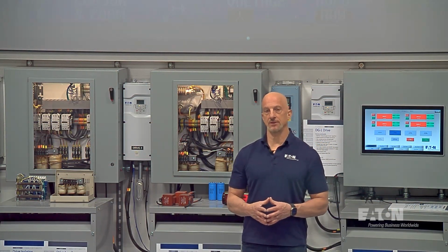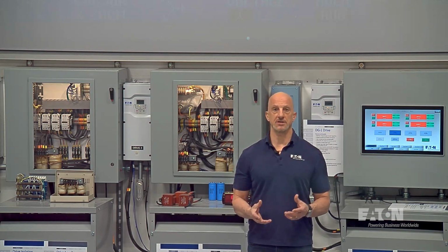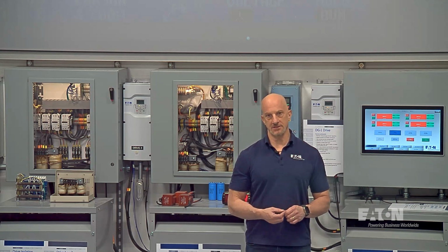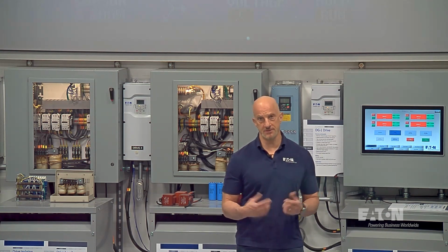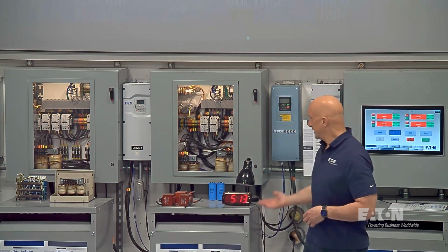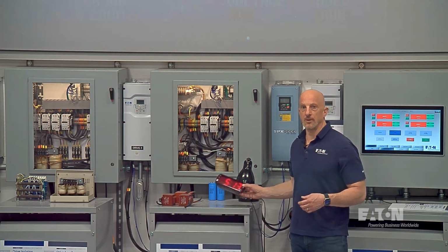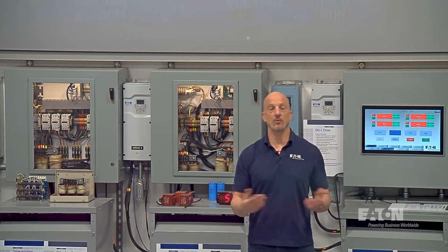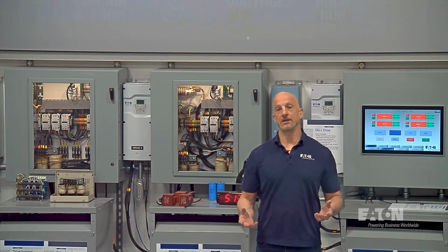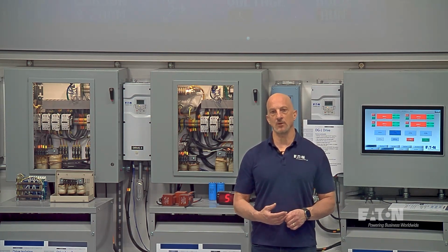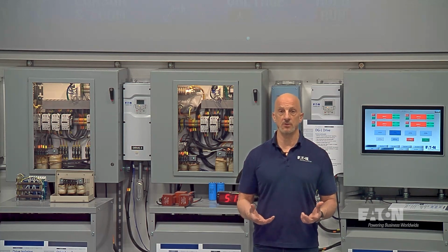So we've talked about multiple zero crossings with voltage distortion and talked about how that causes misoperation. The specific things that we like to talk about with multiple zero crossings are things like sine wave distortion causes things like digital clocks to misoperate. So we actually heard a story about digital clocks misoperating where the workers got to go home early. So I guess in some cases maybe it's not a bad thing. But in some cases like welding applications and other things, it could be a real problem.